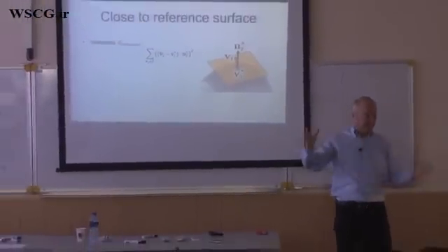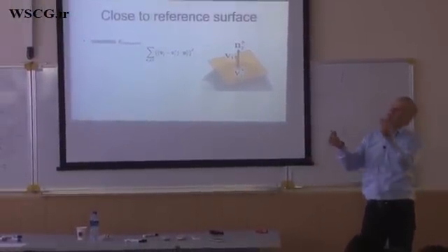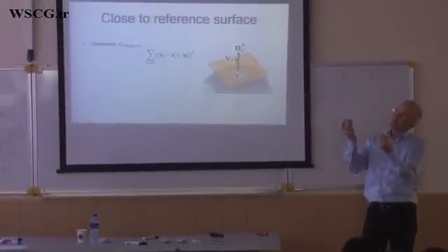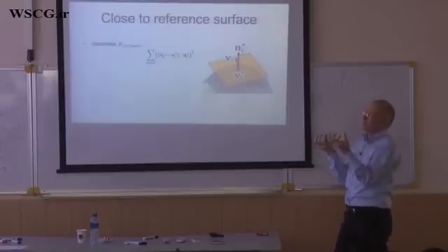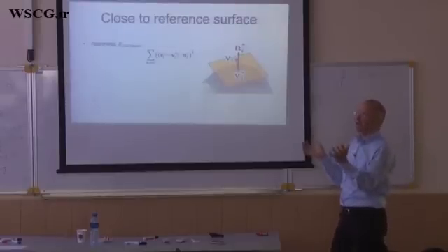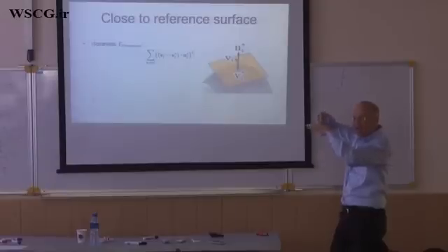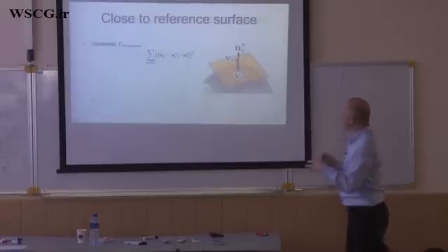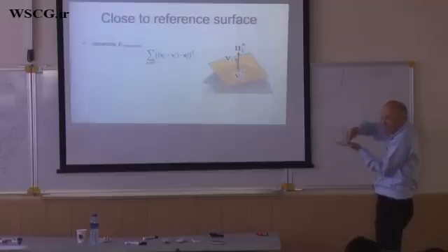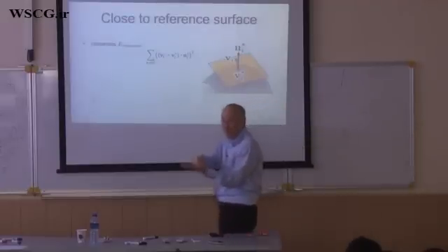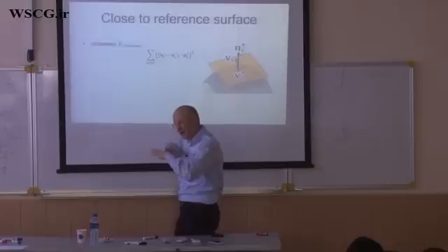If you have a design surface and you would like to achieve a design location of vertices which stay close to the design surface, you must allow your vertices to move along the surface. And if you always make your points close to the closest previous point, you somehow stick to the surface too much. And this tangent plane allows you the gliding.